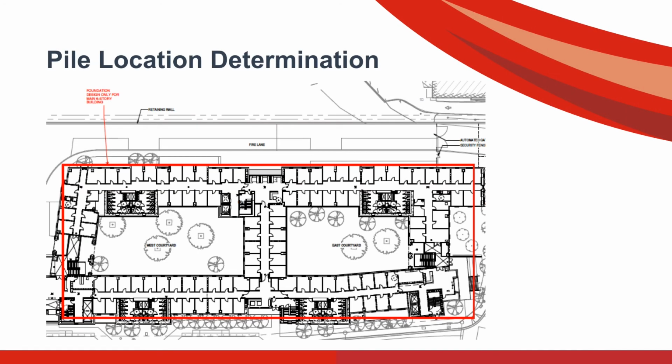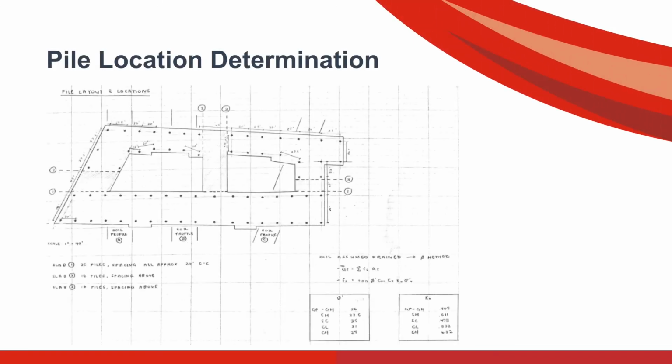A deep foundation was recommended from the geotechnical investigation due to poor quality soils and proximity of local fault lines. Having only been given one story of the building floor plan, it was decided to assume all stories the same and use projected column locations to determine pile locations. As pile reinforcement should extend directly into column reinforcement, most all piles were placed directly under column locations. As seen here, piles were placed all around the building pad perimeters. Spans between piles on the pads were not large enough to require additional piles to support building loads. As a result, the piles were placed as shown.